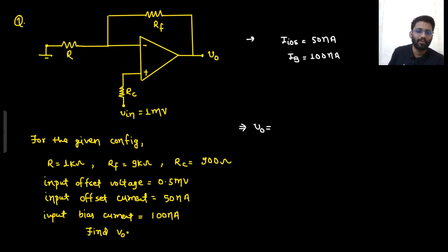Well and good. Then we saw this particular problem. Here we saw that offset current is given, bias current is given. So what is this bias current? That is (IB1 plus IB2) by 2. And what is this offset current? IB1 minus IB2, the modulus. But you don't know the direction of the current, nothing you know. But you know one thing, that compensation resistance is connected. If that compensation resistance is connected, that means it will reduce the output because of the bias current.